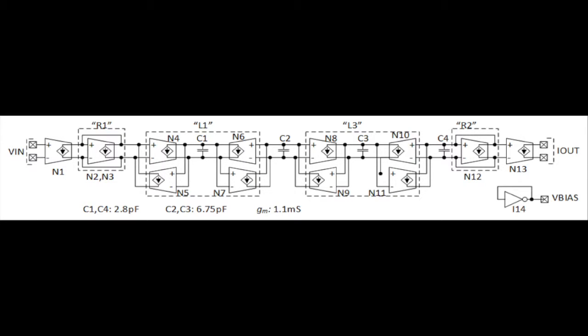And now, a brief discussion on the chip design. This analog continuous time fourth order Butterworth low-pass filter was constructed based on a RLC passive component prototype. Since inductors and resistors are rather large in silicon, they are replaced with active circuits. Prototype filter resistors are replaced with unity feedback transconductors, and inductors are replaced with transconductor-based gyrator C active inductors, as